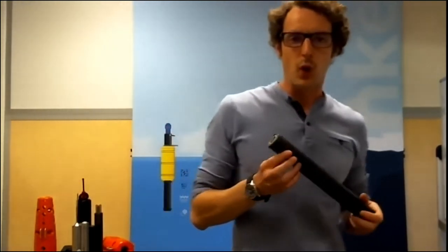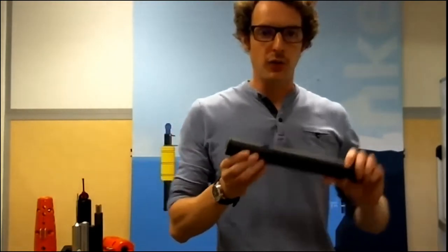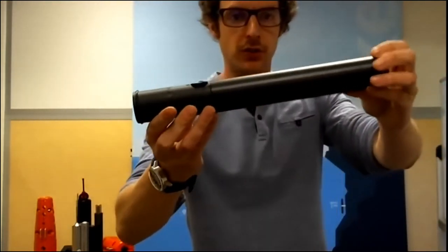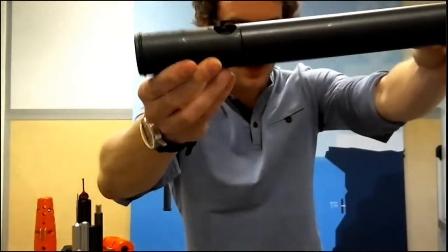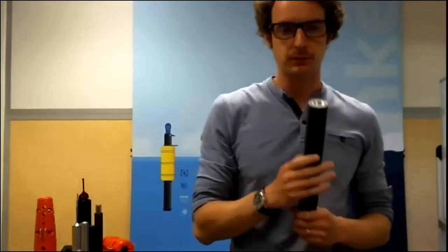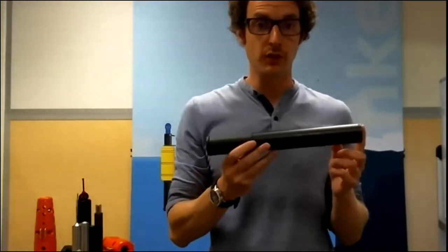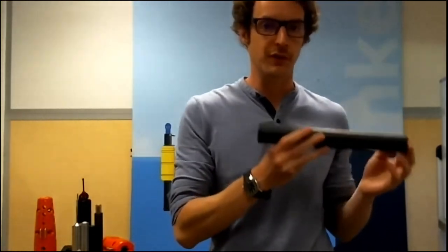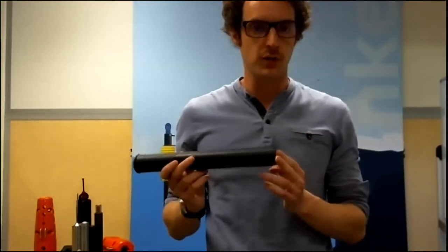Then we have what we call the optical Ysense. So as for the Ysense CTD, you have the pressure sensor on the side, and in the front you will have an optical sensor. So we have Ysense TBD to measure turbidity together with pressure and temperature, or also now coming up the Ysense DO to measure dissolved oxygen. So you have two versions also for these sensors, one for 50 meters and one for 500 meters.